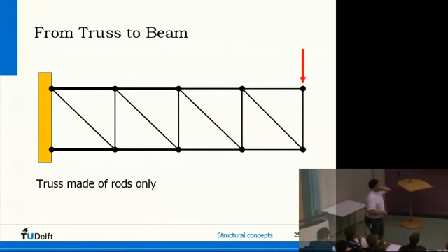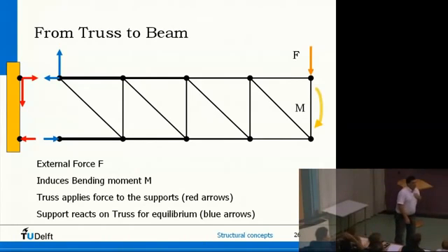No, maybe not. Well, here you have actually more or less the same system, but now you use diagonal bars, and here it is split in forces and bending moments. So if this is my beam, this is my object, there's one external force, and that's this force. What I need now is reaction forces on that end that result in the fact that my beam is maintaining its position. As soon as there's no force and no moment equilibrium, the beam will move or rotate. Yeah? So first, if I look at equilibrium in vertical direction, I do have a force here, so I need a counteracting force somewhere also in vertical direction. And here it is. This force plus that force means that the whole product cannot move in this direction.